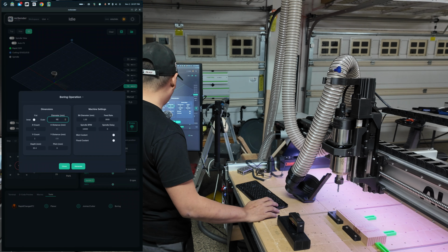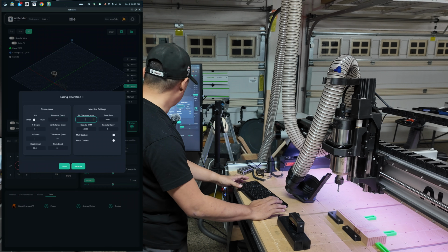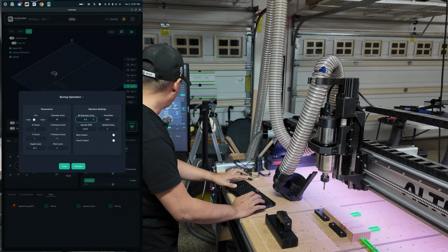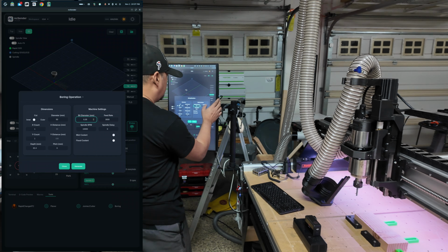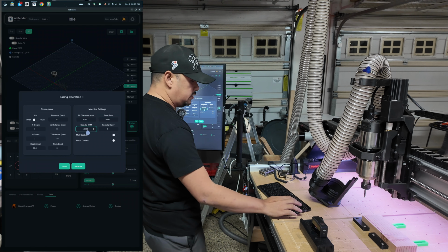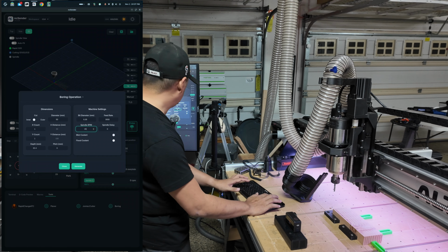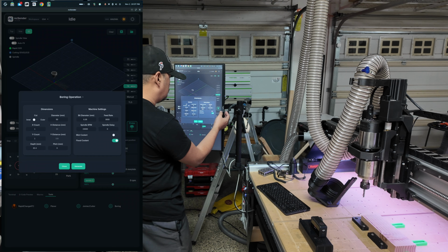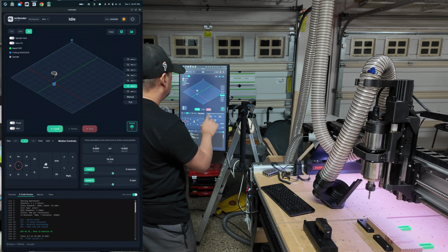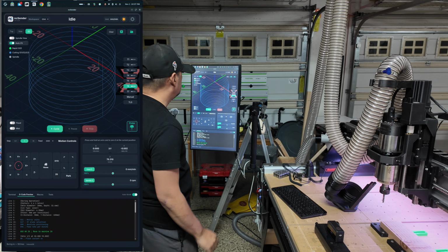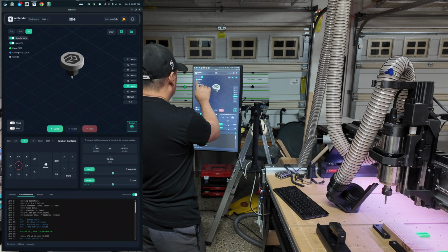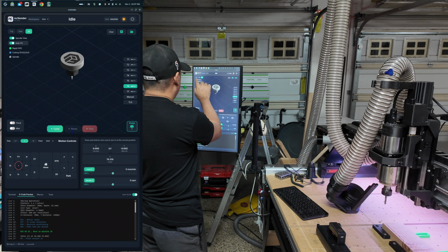So I only need to do one hole. You can also do multiple holes, but on this demo, I'm just gonna do one. And 6.35. Feed rate is 3000. RPM is, let me just, this is 15 R. And then I want to do a coolant plug generate. And then let's auto fit. Spindle view. Auto fit.